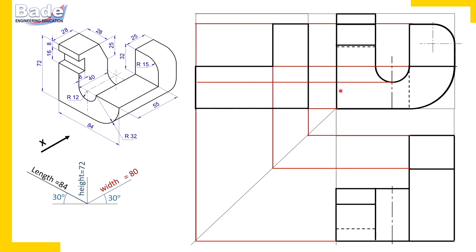This is the front side and this is the back side. So from the front, 40 millimeters parallel to width, you can measure independently. I generally prefer measuring independently for smaller details, and otherwise you can take projectors. Since you have already measured 40 millimeters parallel to width here, you project it here. So this is how we got 40 millimeters parallel to width, and complete the dotted rectangle.